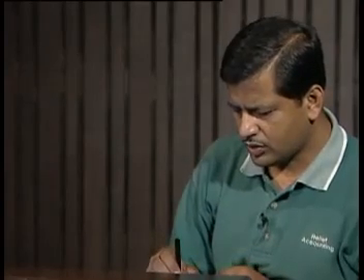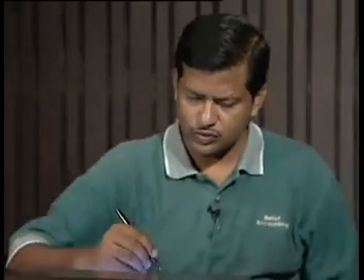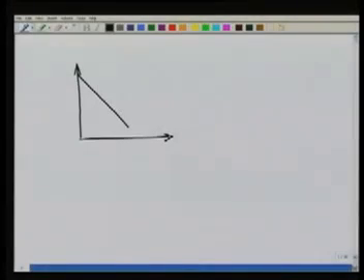So in this lecture we are going to go further with our definition of higher order shape functions for two-dimensional problems. So remember we were working with the triangular elements. So here, how do I construct a higher order approximation that is an order greater than 2 for a triangular element? So what we do, again, is the same thing that we had been doing as before.